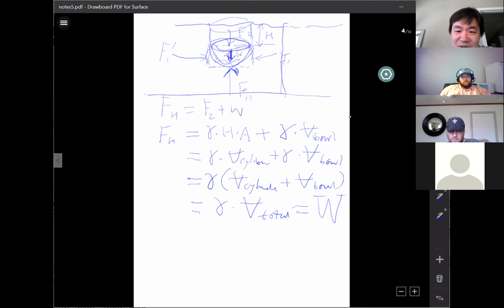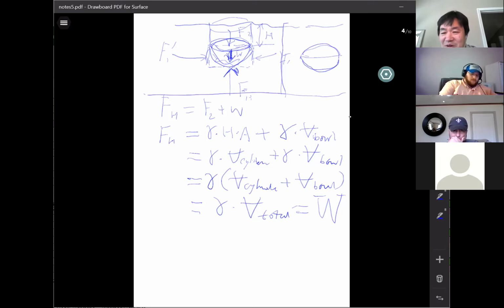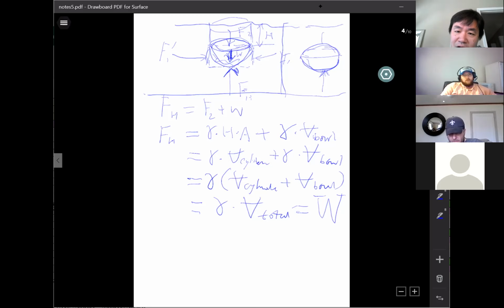extending this case into two surfaces, top and bottom, an enclosure. You know, I'm leading to the buoyancy, okay? The enclosure. So you have two surfaces that is divided into two halves. One is the bottom half. It is actually the hydrostatic force, exposed to the outside of the water. So water applies the force to the surface like this. And for the top surface, you have a water force going downward.